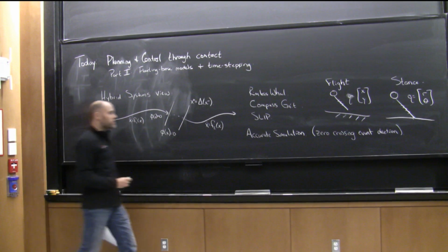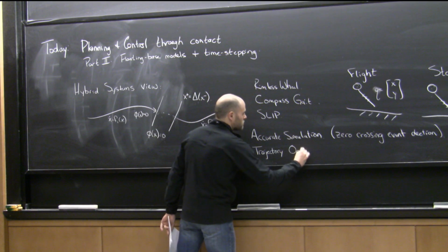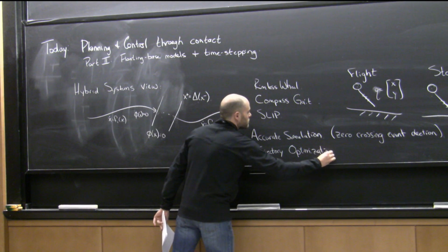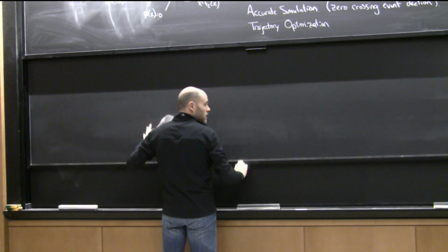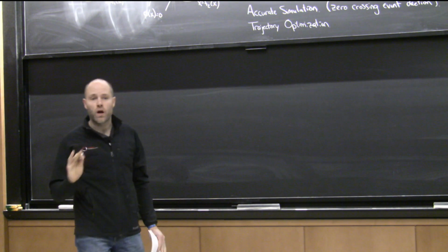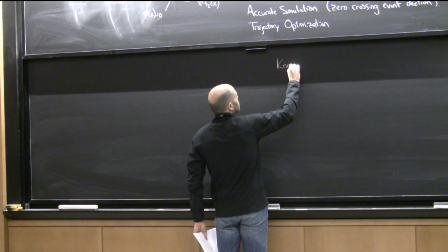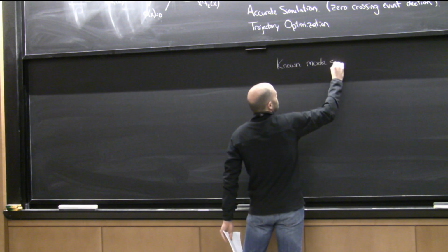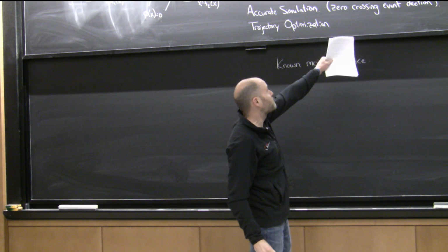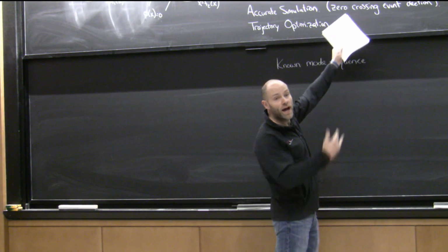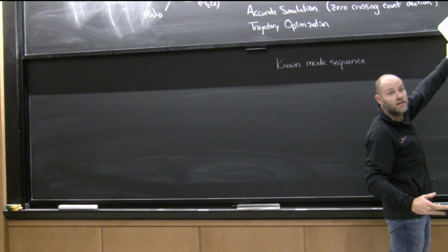For trajectory optimization, this was also really nice. We could basically take the tools we already had, and at least for the case where we know the mode sequence, then for instance in the SLIP model we could populate some constraints in x and y, the first k constraints in x and y, the k plus 1 to whatever constraints in r, theta, and so on.